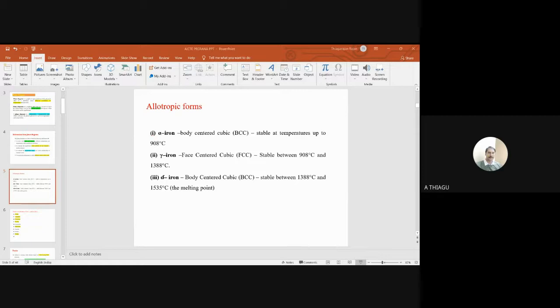So what are the unique properties of martensite material? It is very hard, with low ductility. We lose the ductile property. Ductile means deformation, so we lose the deformation property because of carbon only. Hardness is increased, and as a result the material changes from ductile to brittle. Anyway, the essential thing is that hardness is improved. So this is one of the important microstructures, martensite.